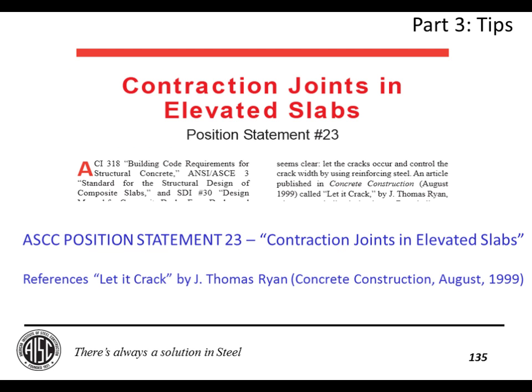To get dosing amounts, for instance, of polymer, microfibers, or steel fibers, you would need to actually talk with the fiber manufacturers to see what a reasonable dosage would be to help limit shrinkage cracking. Okay, great, thank you.